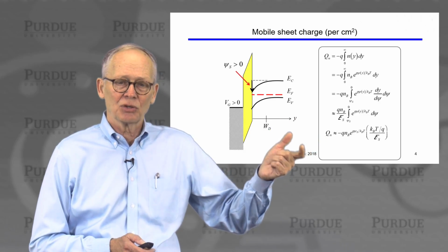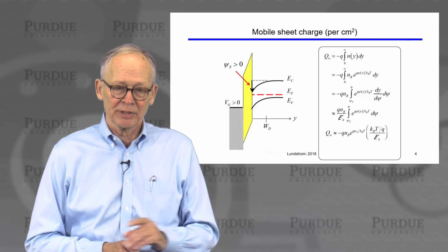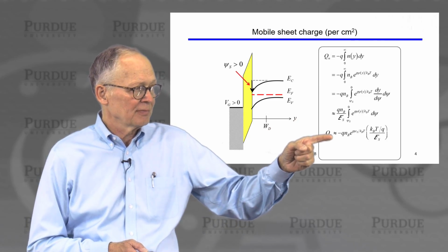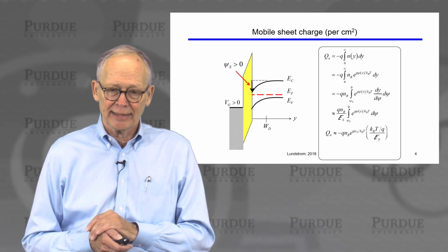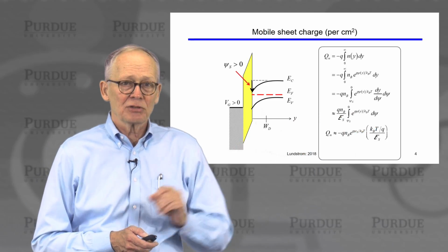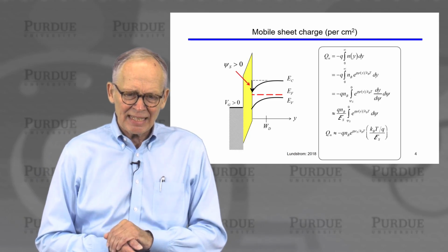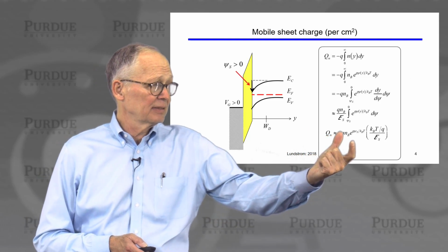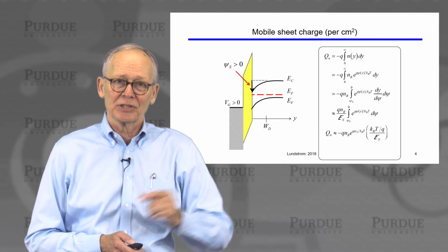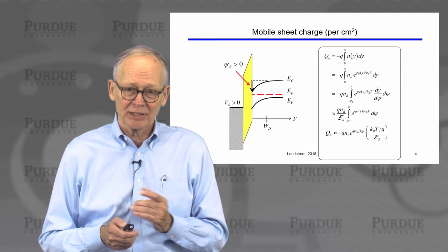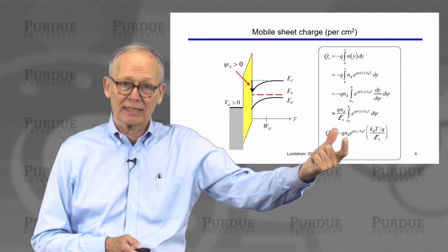The result is that the total charge of electrons per coulombs per cubic centimeter is minus Q times the concentration in the bulk, Ni squared over Na, times this exponential factor e to the q surface potential over kT. The units of these terms are per cubic centimeter. We are looking for a charge per square centimeter. So the other terms have the dimensions of length.